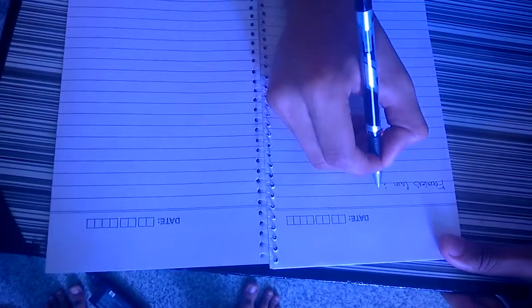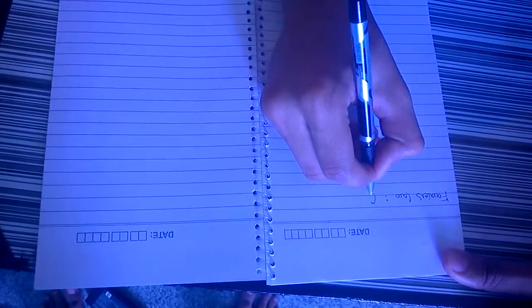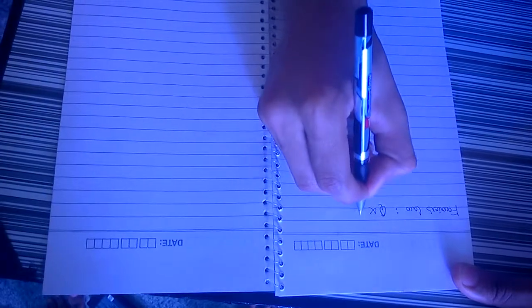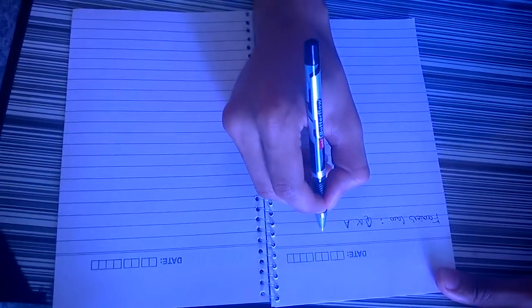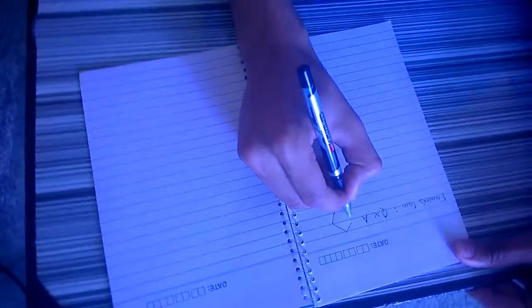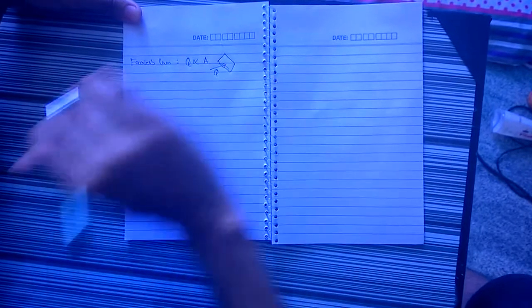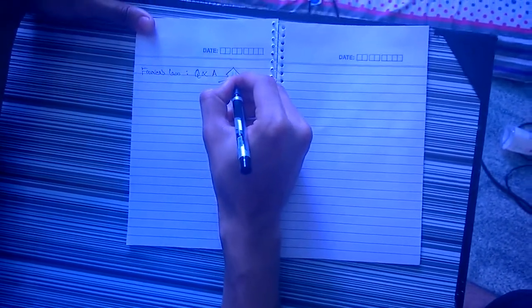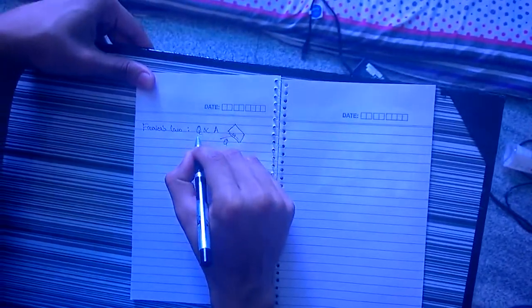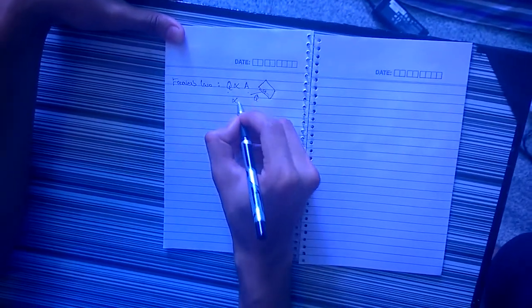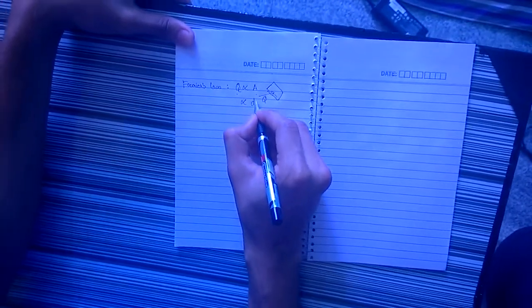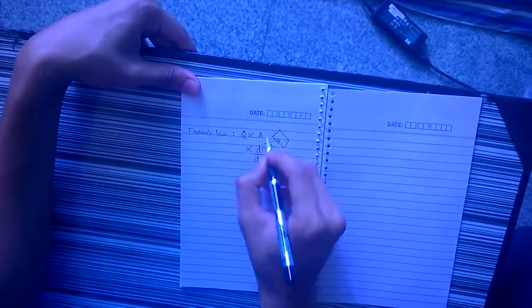Now Fourier's law basically tells us that the heat Q is proportional to the area which is normal to the surface where heat is getting transferred. So if this is your surface and Q is transferring in this direction, this area is considered. So Q is proportional to A. It is also proportional to the change in temperature in the direction which we are considering.